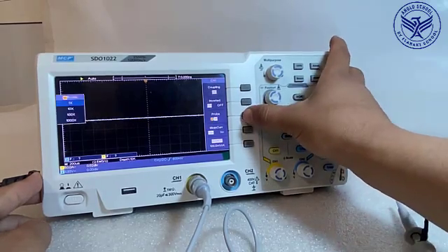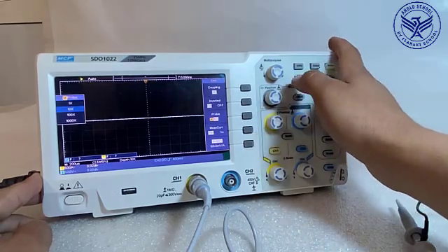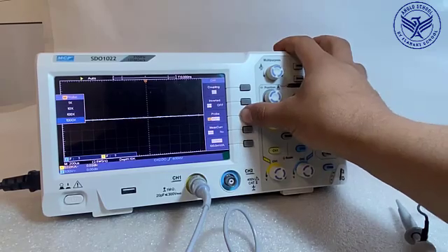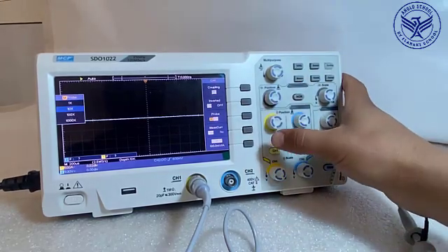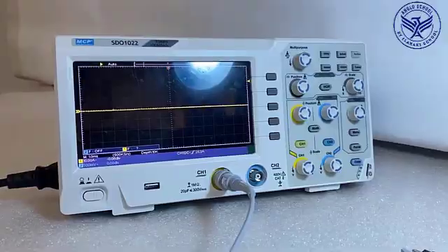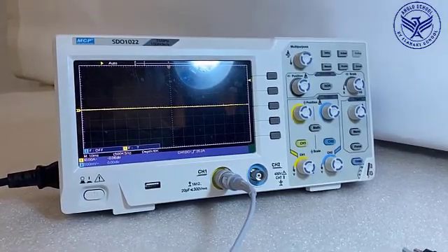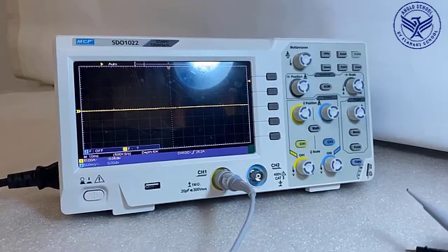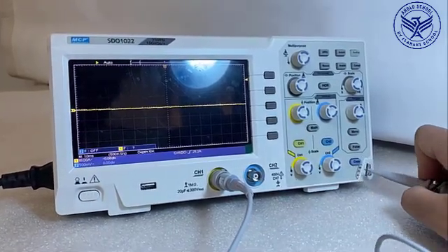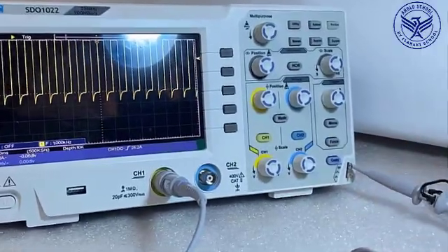Press the trigger menu button. Make sure type is set to edge and source is channel 1. Check that slope is set to up edge. These tell the scope that we want to start our measurements on a rising edge of a signal on channel 1. Most scopes come with some kind of built-in frequency generator so you can test your probes and tune the compensation capacitor. This one happens to have a 1 kHz square wave generator we can use.